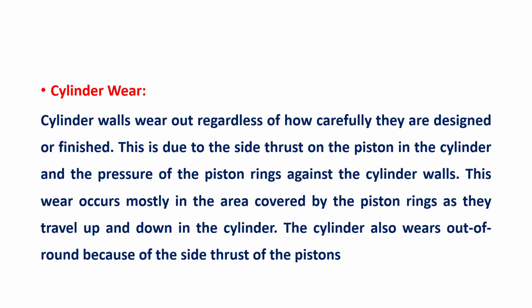Next is cylinder wear. However we finish it, we can't avoid cylinder wear, because the cylinder is subjected to side thrust from the piston. The pressure of the piston rings also acts on the cylinder walls, and the piston will be moving up and down, isn't it? So the cylinder wears to a taper.